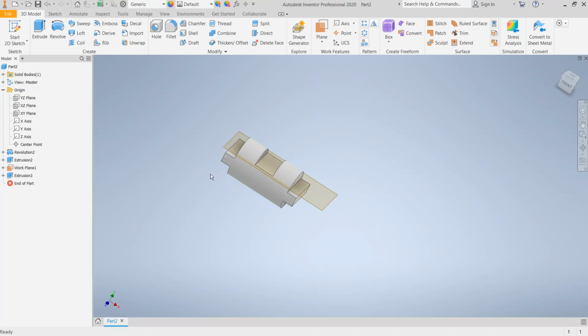12. We have to create a work plane that is at a distance of 12 millimeters from the XZ plane. So let's create that. Select work plane offset. So we want to offset from XZ plane, and then we can just change the direction of the arrow. So now it's going to be -12 since we're going to the other direction. -12.